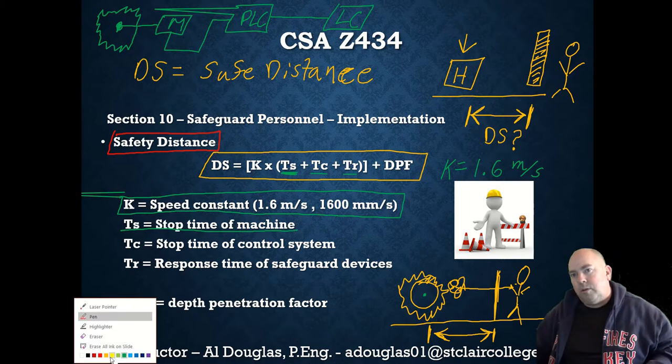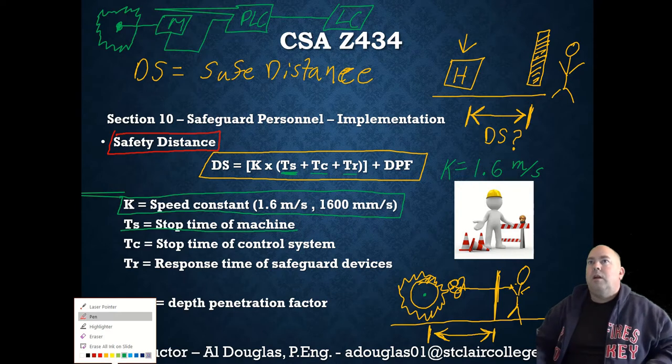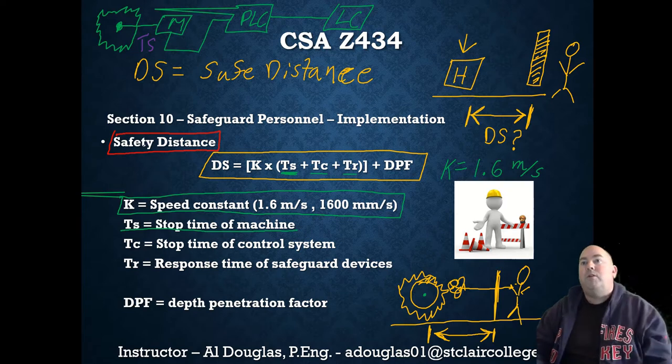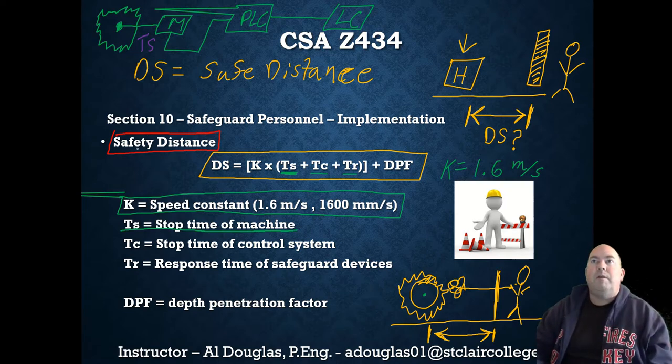Let's say those are all our factors that are involved here. So basically, as soon as we tell this motor to stop, this has some physical time for it to stop. This is the longest of these 3 times. And that one is called TS. Okay? So between the time that our motor actually cuts out to the time that this thing comes to a complete stop, that is TS.